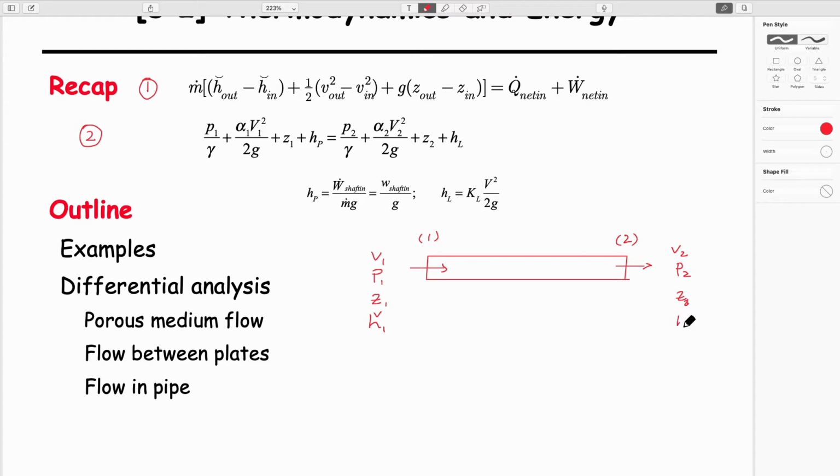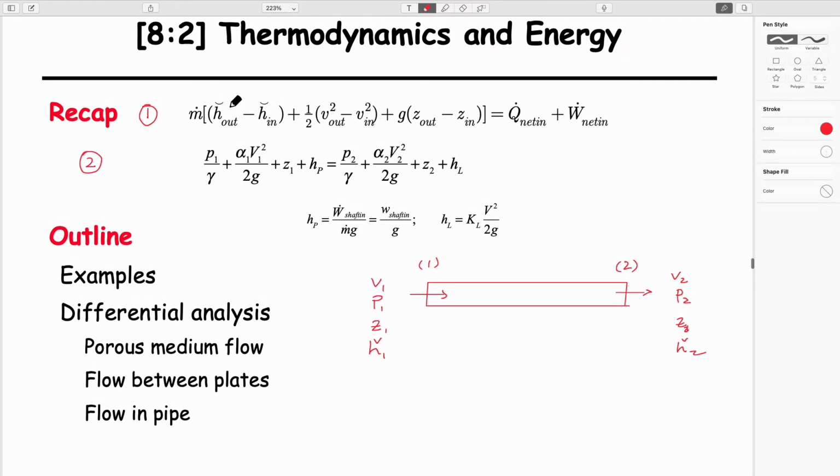Enthalpy, as we've defined it, and you would know this, is equal to internal energy per unit mass plus pressure over density, by definition. If we write it out a slightly different way, this is the first law: change in internal energy is equal to heat rate in plus mechanical energy rate in.